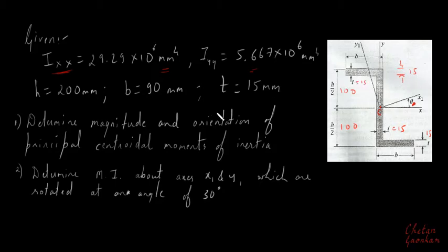And then he's saying that B is 90 mm. That means this distance from here to here is 90 mm. Since this is a composite section, the way we were solving the problems in centroid and moment of inertia, we are now already aware that this kind of problem can be easily tackled by just dividing this into shapes whose properties are already known to us.